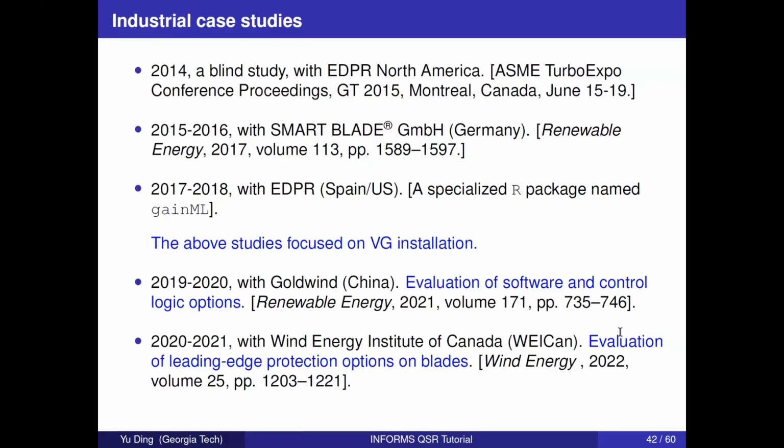So you can use that date as a kind of demarcation mark, right? The before and after. They didn't really tell us how many turbines had been modified with this retrofit, and of course they didn't say which turbine was modified. So we have 4 choices, right? There's 0, 1, 2, 3. It's still a choice because even though they said some turbine was probably modified, it could be 0, right? There's no turbine being modified. So we applied our analysis and eventually we identified one single turbine. We said that turbine has been given this VG installation, the other 2 turbines have not been given the VG installation. And it turns out we identified the right turbine, okay?